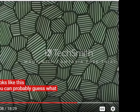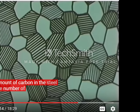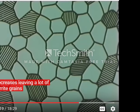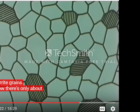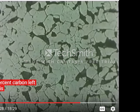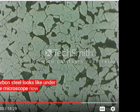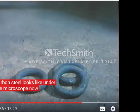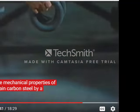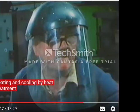You can probably guess what will happen if we now reduce the amount of carbon in the steel. The number of pearlite grains decreases, leaving a lot of ferrite grains. Now there's only about 0.1% carbon left. And this is what a similar piece of carbon steel looks like under the microscope. Now we can change the mechanical properties of plain carbon steel by a carefully controlled sequence of heating and cooling, by heat treatment.